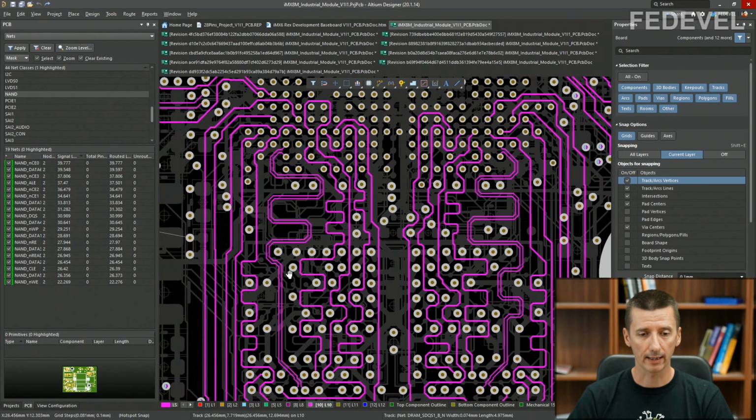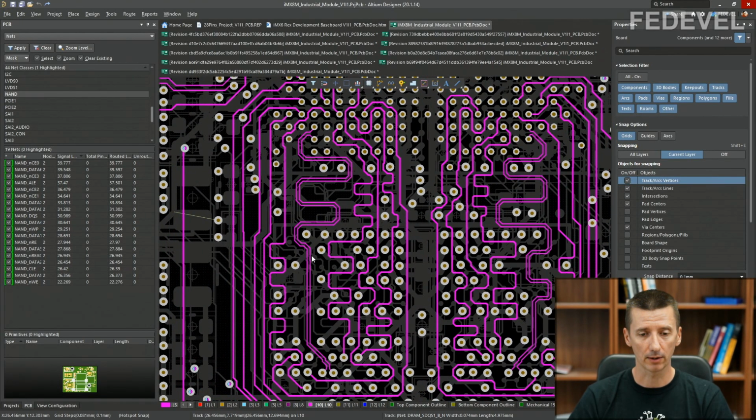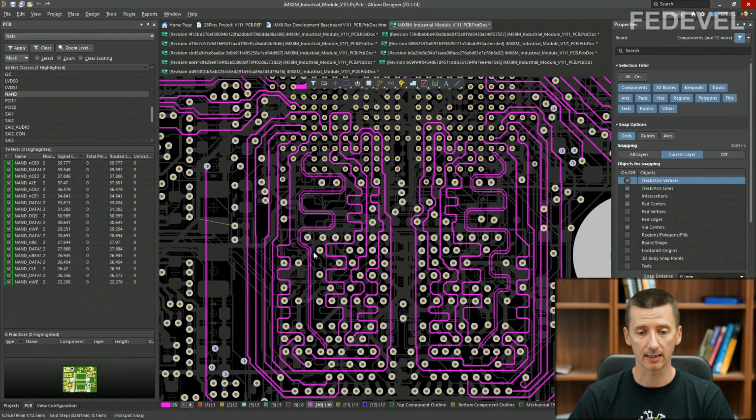because when you are doing a draft or preliminary layout of a memory interface, you would like to see how much space you will need to route this interface properly. So even this length matching is not perfect at this moment. These signals are length matched just approximately, no precise length matching. You still would like to see how much space you will need to do it properly.